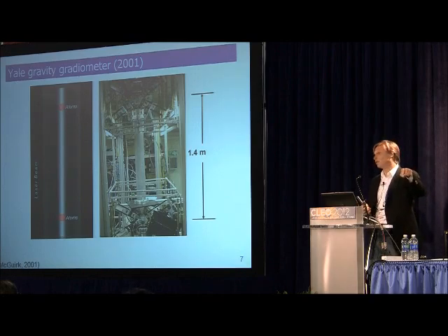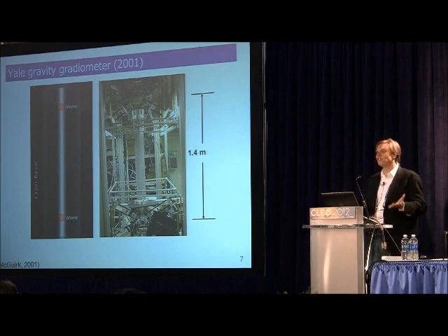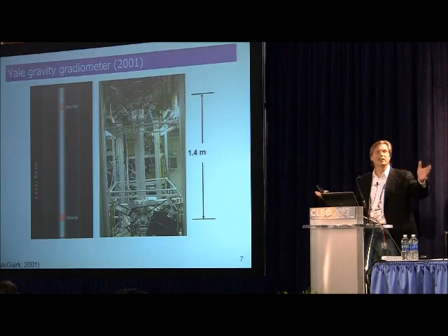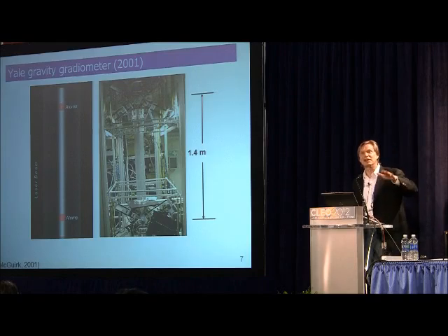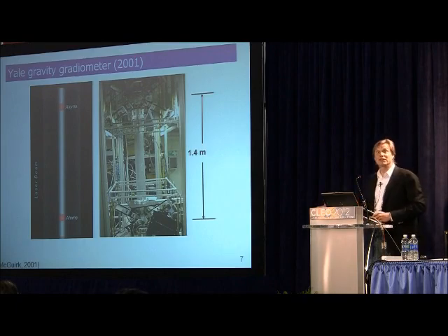If you put an accelerometer on the floor of this room and ask how much it is shaking up and down right now, you'd find it would be shaking at about 10 to the minus 4, 10 to the minus 3 of little g. You don't feel that right now, but there are hums, all those lasers and power supplies and people milling around making the floor shake. I have an accelerometer that can do 10 to the minus 11 of little g. Is it going to do me any good to have 7 orders of magnitude more sensitivity when there's environmental noise?